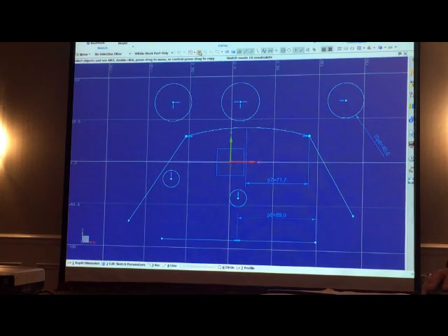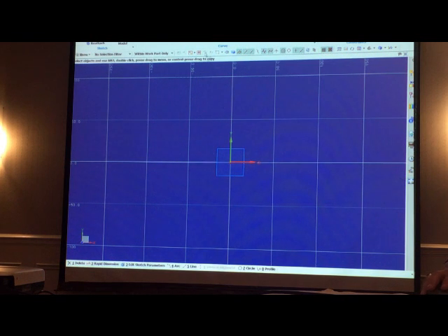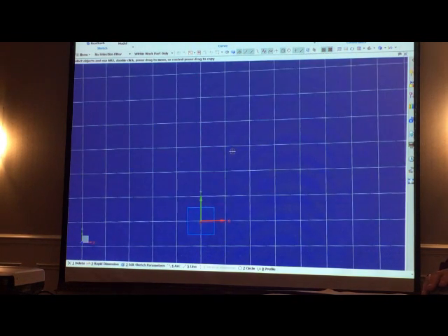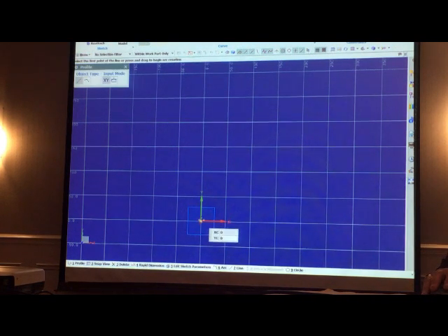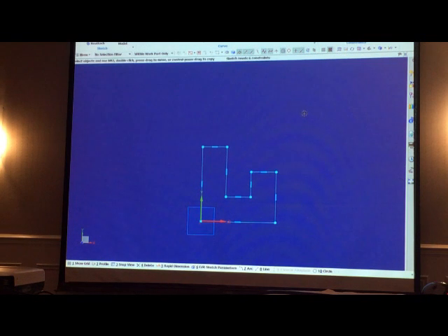Okay, I know you're going to like this one. Take yourself back to the first day of NX modeling class, and they teach you about the sketcher. And they say, well, the sketcher is really easy to use. All you do is draw exactly the shape that you want. Get all the proportions right, get it so it looks like what you want it to look like. I'm going to turn off the grid here so you can see better what I've done. Get this shape right, and then once you've got everything correct, go put the dimensions in.